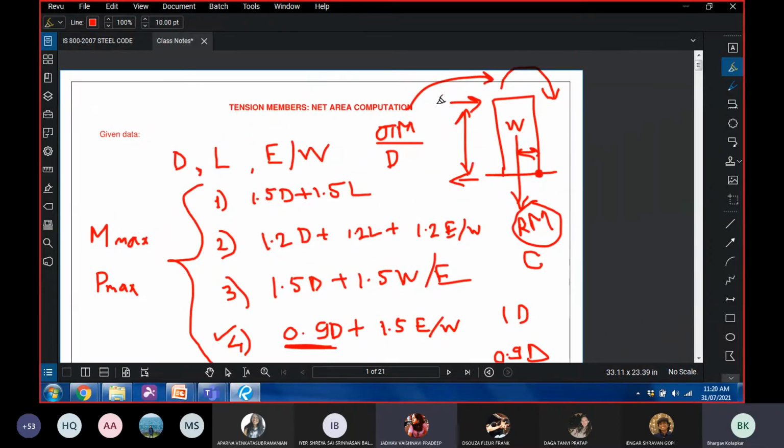Okay. So lateral load, whether it be earthquake or wind, is going to try to overturn the structure. The self-weight of the structure is resisting this overturning moment. So if I say that the self-weight is acting at the CG of the building, so this is the self-weight, and this is the point about which it might overturn.